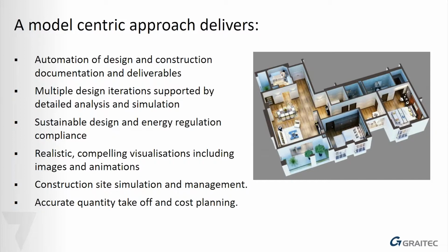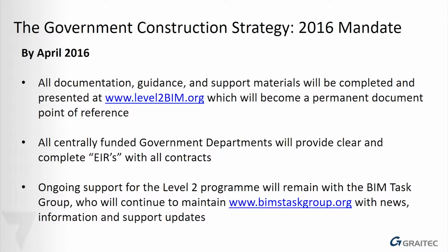And then probably one of the best features is the quantity takeoff. So if you basically place an object within a BIM model, we can count it. Within Revit in particular, it will count everything that's in there. It will give us very accurate takeoffs for brick, block, plasterwork, any material that we're using, we can get very accurate takeoffs.